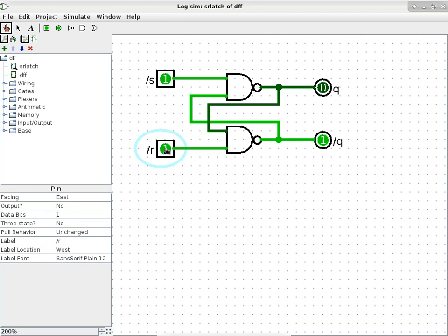In hardware design, this is called a race condition. Race, R-A-C-E. It depends on who gets to the finish line first. And that is usually a bad problem to have. When your hardware has a race condition, it usually is a bad situation. Most of the time, that kind of bad situation means the computer hardware involved would not work in certain conditions. Like when you heat it up, it will start to behave differently, because when you heat it up, transistors will change their actual latency. Temperature can change that.